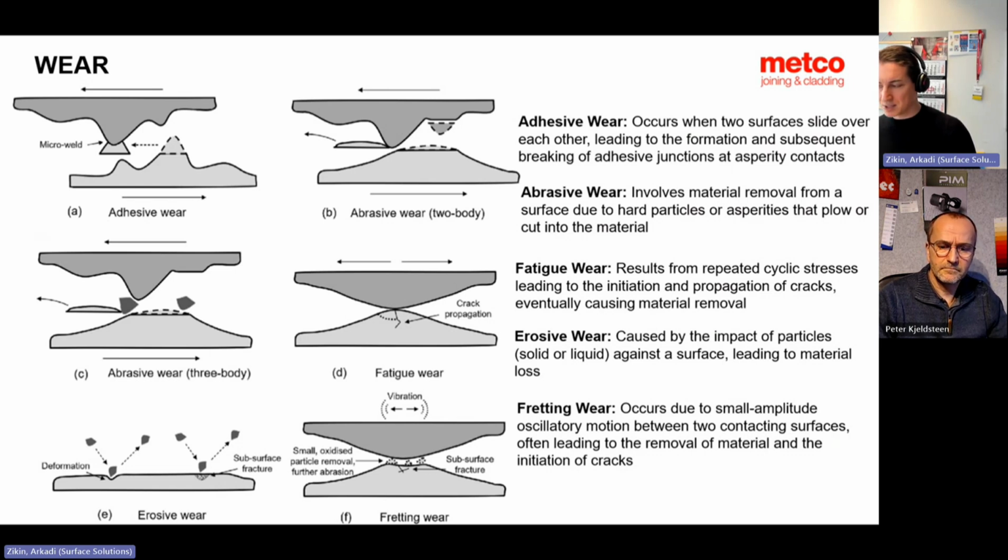We don't have to stay in details, but it's very interesting that depending on which wear mechanism is causing it, different materials behave in a very different way. And this is what makes our life as people who do coatings for protection against wear or try to develop materials; we always have to find a compromise and try to understand what our customers really have as their issue. If they have erosive wear or fatigue wear, it might not be that you use the same coating.